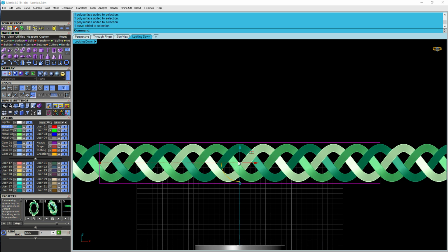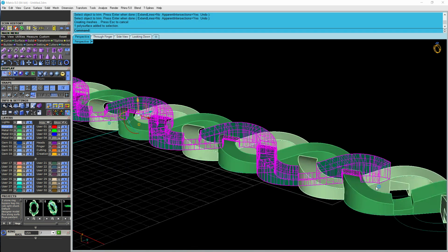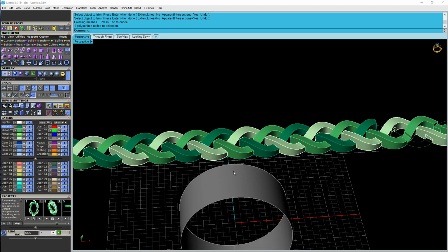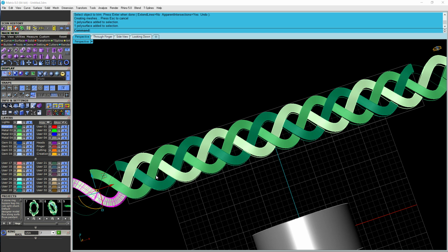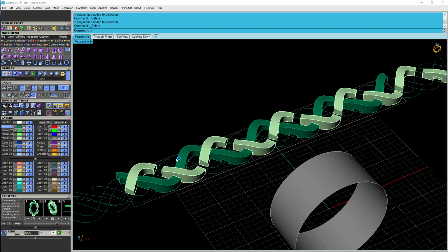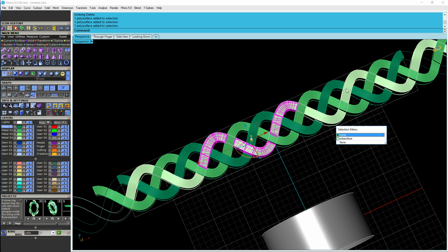And then this is gonna be the solid one. So we'll select this curve. We'll say trim and trim. And we'll keep that open. That way, like I said, it joins up at the bottom. That's gonna be the solid one. And then we'll get rid of that one since it's outside. This one. And just two of those will work.